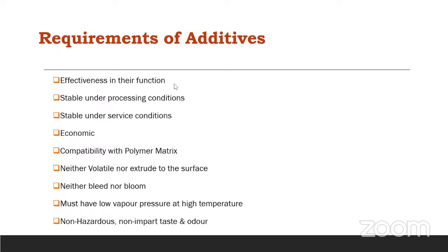Fillers are again one type of additives, like calcium carbonate, then carbon nanotubes. These fillers can help in reducing the cost of the material by increasing the volume of the material. While incorporating them in the formulation, the concentration of your basic material is reduced.